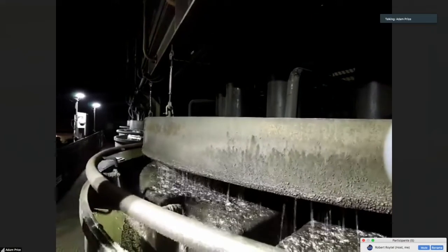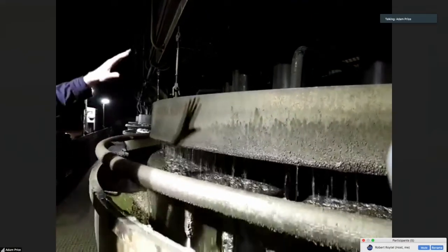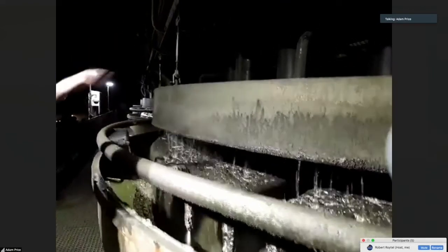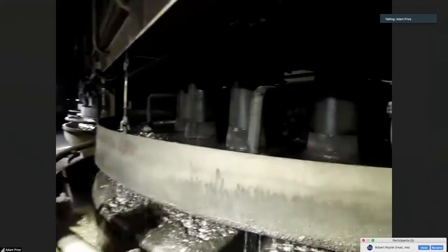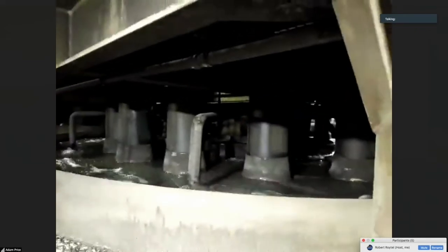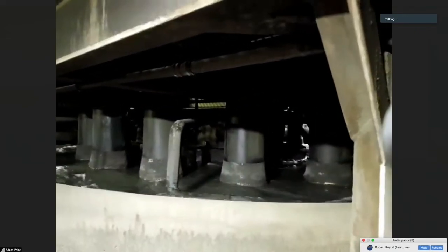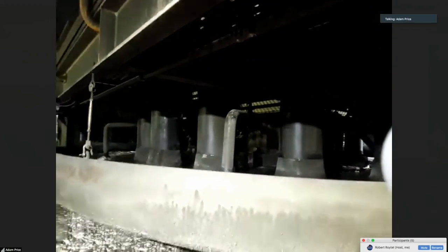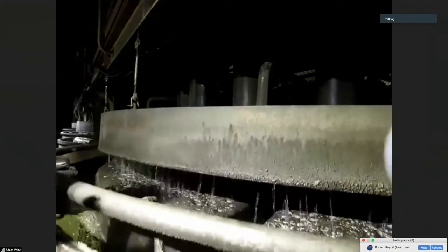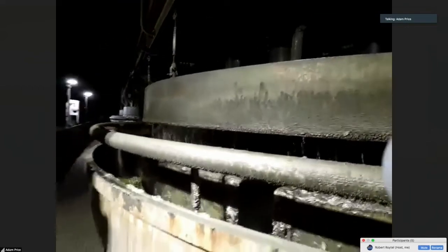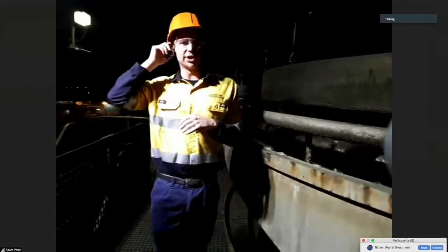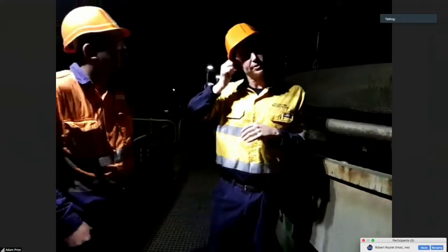So the other real main advantage here is no agitation in the tank. As you can see, no rotor or anything in the middle there, which creates really low turbulence within the tank. That gives the particles the best possible opportunity of getting to the lip and being recovered into the concentrate. So that's probably the main crux of the operation I wanted to talk about. I'm just going to pass the microphone quickly on to Christian to ask him a few questions.